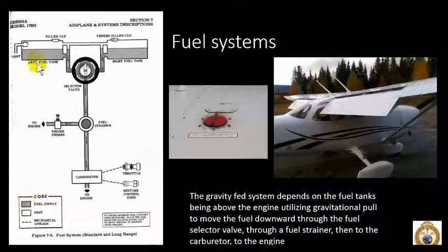Now this dark region is a fuel supply. And then this lighted area is a vent. Like we told you, that float-type carburetor has a vent. There's also a vent here and a vent here. So nothing gets vapor locked. We let the system breathe.